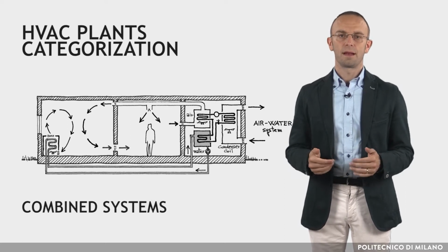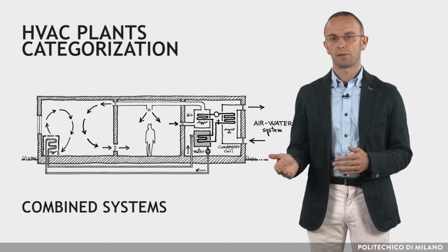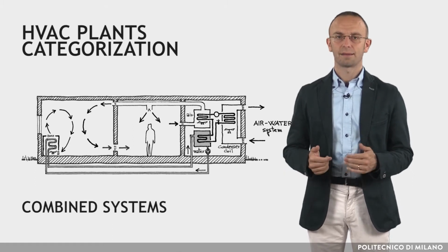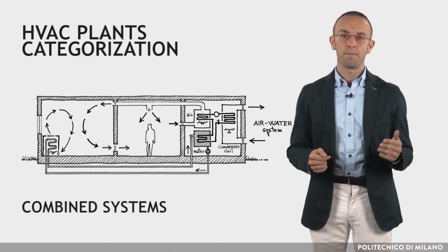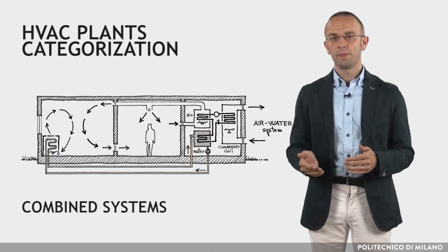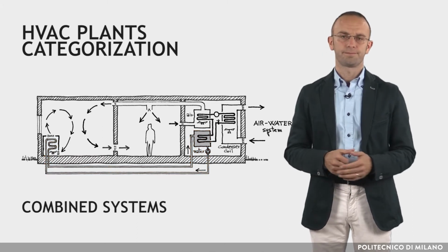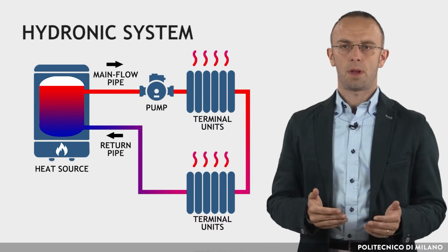Combined systems are a combination of two or more of the above-mentioned categories. The most common are the air-water systems, where sensible cooling is usually managed by the hydronic system, while air provides humidity control and ventilation. In hydronic systems, water is used to transfer thermal energy.